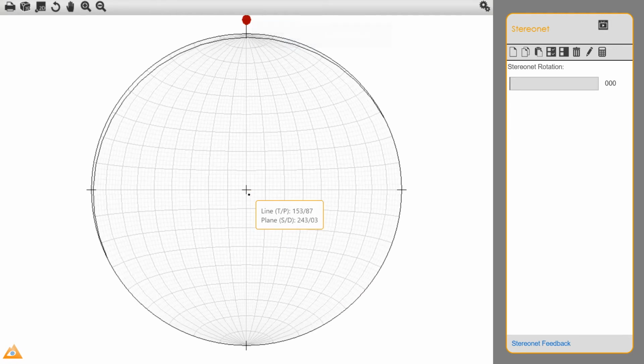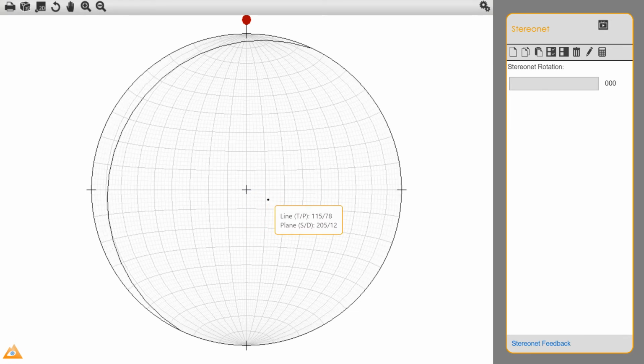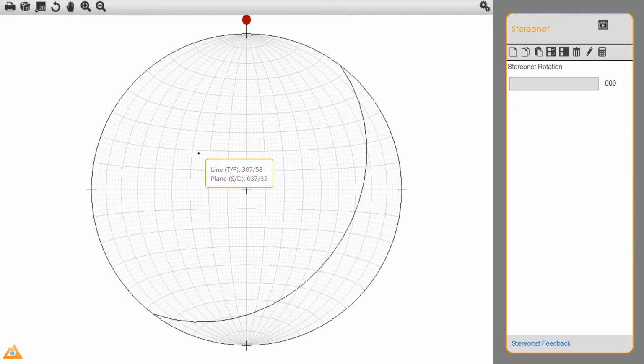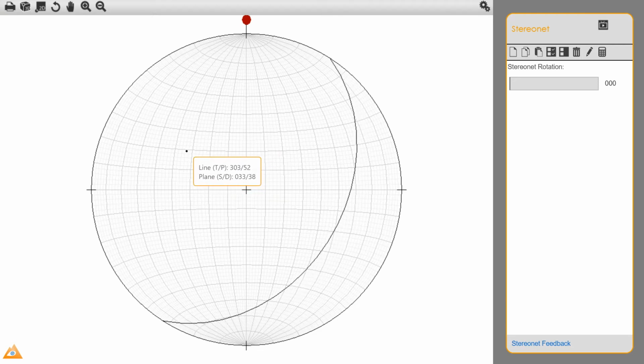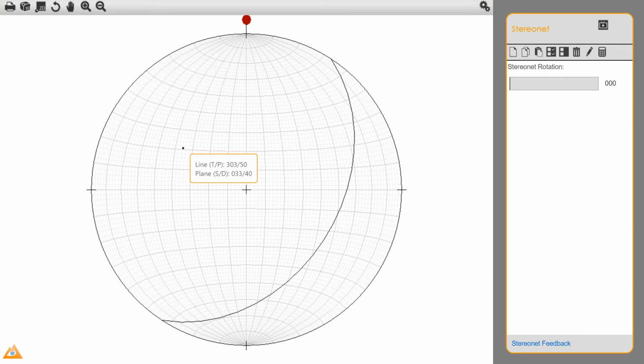Then we said points closer to the middle. This is no dip. And then we were trying to see this plane of ours with strike of 30 degrees. Let me see, was 30? Yes, 30 degrees and dip of 40 degrees. So let me find that. I'm at the strike, and now I need to get the dip. Okay, so the dip is going to be somewhere over here.